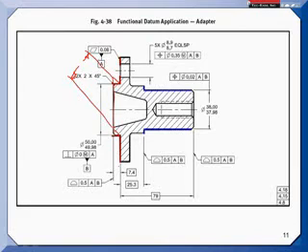So, like I said, on something like that sheet metal, I'd leave the perpendicularity off because you can't prove whether it's right or wrong anyway. But you get into a part like this, I'm going to put it on there. Did that make sense? Yep, it does. Okay.